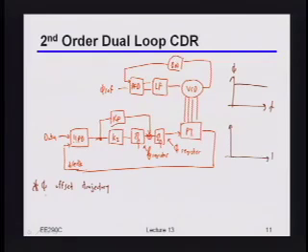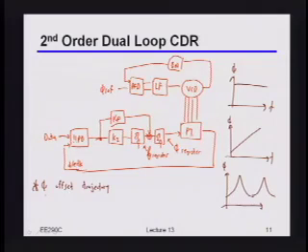If I have a plesiochronous system, then my trajectory has this ramp. So I better build my loop so that it can estimate both that offset and the ramp rate. And in fact, you can even do more sophisticated things. For example, sometimes people have phase trajectories that even look something like this. Okay? Anybody know where that happens to come from? The offset is also varying.